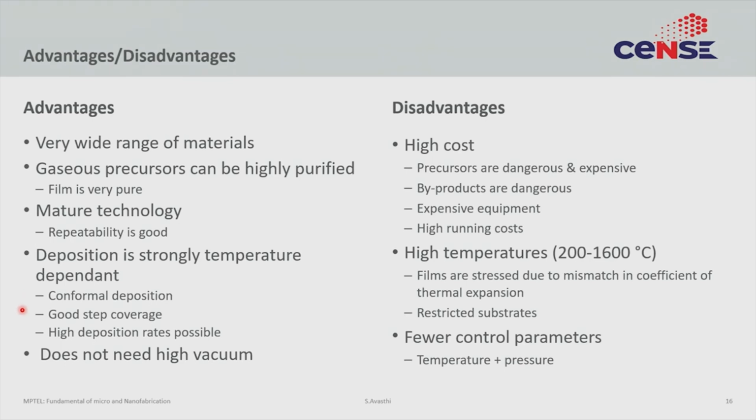And of course, high temperature also means that there is a short list of substrates that you can reasonably use. We have discussed the issues of contamination a lot in the past. So, steel may not be a very good substrate for CVD, because steel has iron, and iron will diffuse at high temperatures, and if CVD requires those high temperatures, then it will contaminate the film that you are trying to grow. So, your substrates must be non-contaminating, and must be able to withstand the temperature. You cannot do CVD at 700-800 degrees C on a plastic substrate. There is no plastic that will withstand that sort of temperature. Even substrates like glass may not be able to withstand that temperature. So, that reduces your options.